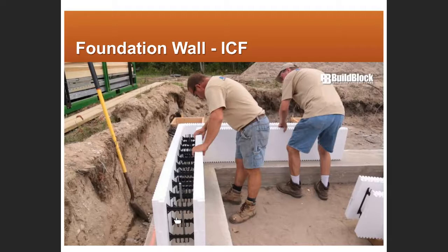On the systems that I'm aware of, sometimes these little black trusses will poke out the other side to give you a place to attach drywall or something else, whatever the finish is, because below grade on the outside, you're okay with insulation, but inside you have to cover that insulation with something else, with drywall to provide fire resistance. But this is really to show that there are a number of different ways that we could build foundation walls, block or brick or poured in place concrete.